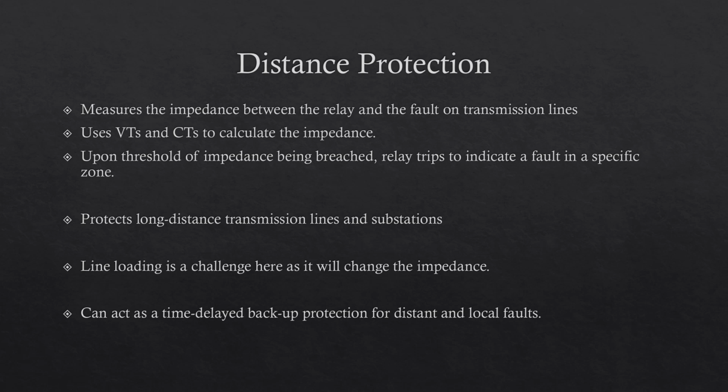Quite useful. However, one issue with this, because it does rely on the impedance, is that, for example, during summer, the impedance of the line will be different to that in winter. So it can be quite a challenge to make sure that this system appreciates that.